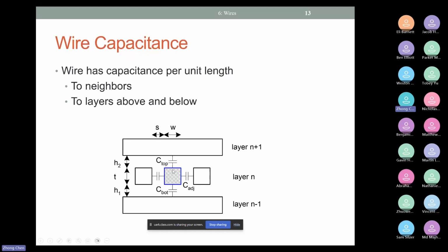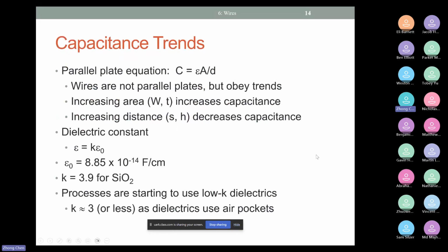So that's why you have the total capacitance here, all right? Adding that. The slides will tell you how to estimate this capacitance value, using the total area and the dielectric constant, which is typically an interlayer dielectric of silicon dioxide, with some variation. But mainly the dielectric constant is very similar to silicon dioxide, 3.9. And then you can have some estimation of the area and the distance.